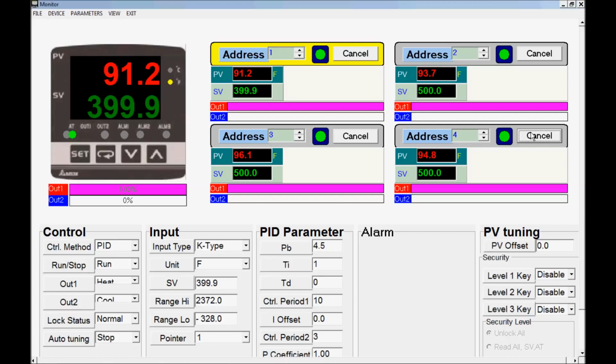and when you look at your temperature controllers, you should see the RX and TX LEDs flashing for the first four controllers. On the next four controllers, only the RX LEDs are flashing.